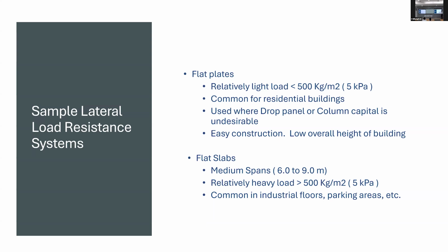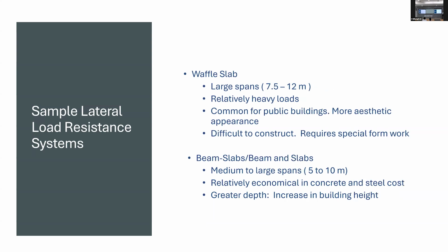Flat slabs are used for medium span, 6 to 9 meters, and of course this is without post-tensioning. You can always post-tension to change the span length range. Waffle slabs are used for larger spans and relatively heavy loads like libraries or storage. They are common for public buildings, with a more aesthetic appearance, but are difficult to construct and require special formwork.